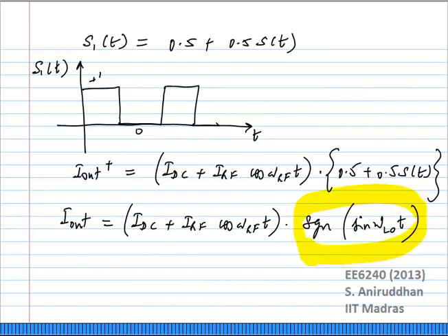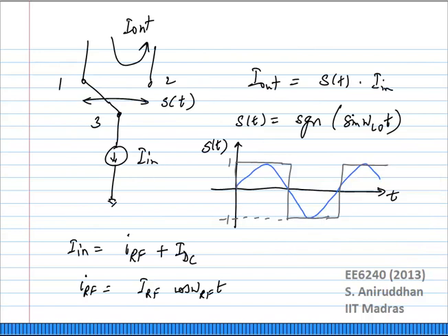Okay, let us look at the original square wave we talked about. One possibility is change in duty cycle. The other possibility is just shifting the signal upwards or downwards. Let us take the second one. Let's say shifting the signal upwards. What does that lead to? It will give you a DC component.